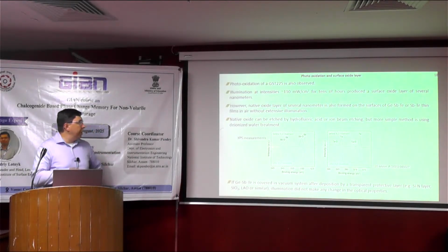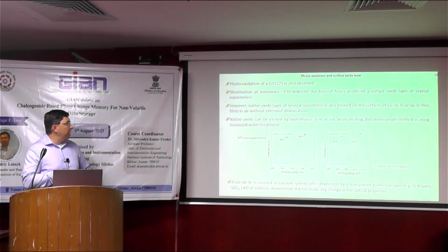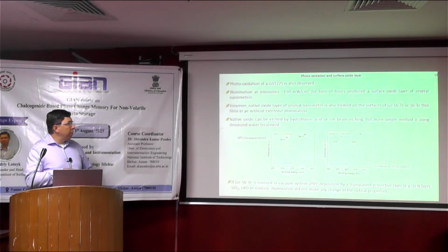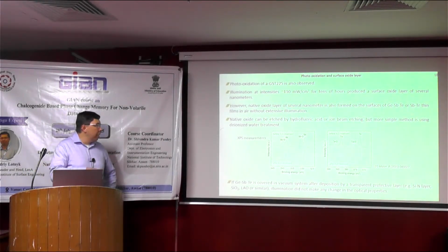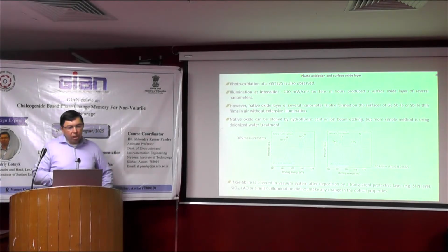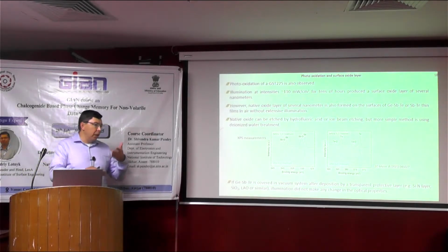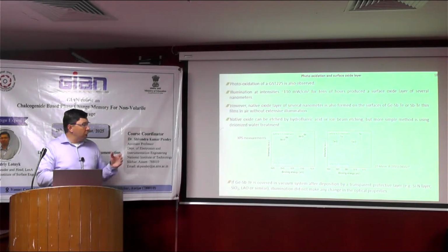You can see here, it can be nicely seen by XPS measurements. This was the case of antimony telluride. Here you can see the peaks belonging to the pure metallic antimony and tellurium, and you can see also the peaks belonging to the antimony oxide and tellurium oxide. So for the application, it's not good because you lose contact again. If you build your device, electric device or optical device, you have oxide in between.